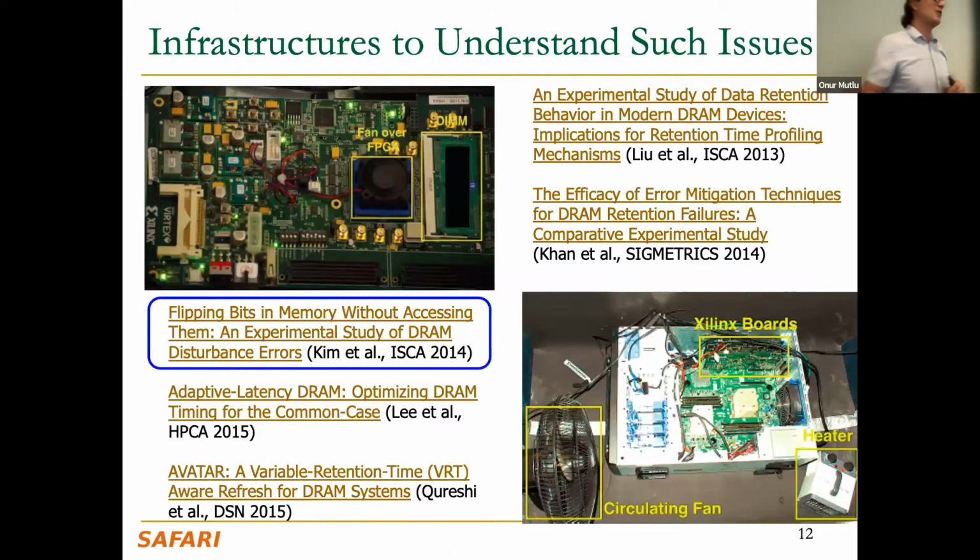that are interesting. So of course, with a large-scale study, you cannot really pinpoint some of the issues. So we also wanted to build an FPGA-based infrastructure to understand some of the low-level issues that happen with DRAM. And we're going to look at retention failures and latency and RowHammer in this. So basically, these are FPGA-based infrastructure where you can modify the memory controller, and the memory controller can change the commands that you can issue to DRAM so that we can test essentially anything that the interface allows. By violating the timing parameters, for example, by not refreshing DRAM, we can figure out different things.